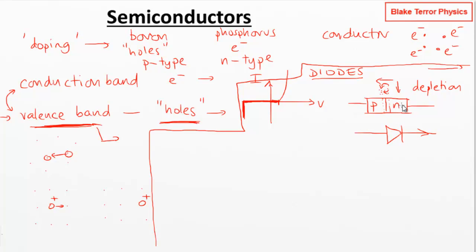This will continue to happen if you give them a little bit of a push. Essentially, if you put a potential difference in the right direction across this junction, you're going to give enough of a push to some of these other electrons that they'll start going across the boundary here, and it will start flowing. You're going to start getting this movement of electrons, and they'll just sort of start cascading, because they have to keep moving. They're not just going to go across. So you think of Kirchhoff's first law, we have to have the same current going all the way through this. So you're getting this cascade of electrons as they sort of ripple through these holes. Now, it doesn't have to be the same electron, but you're getting this movement of electrons, which you, of course, as I was saying earlier on, could think about as being movement of holes.